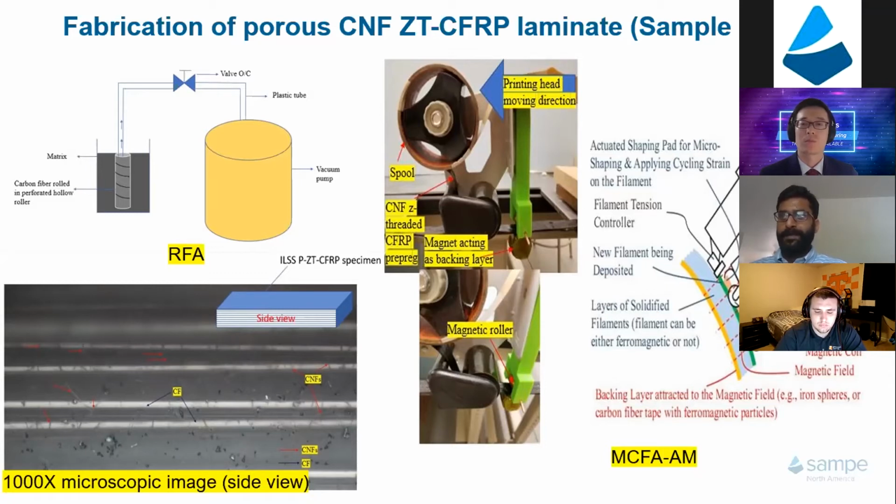But once the acetone is removed, the monomers get close to each other and they start to react. So there's a threshold where you can remove acetone without curing it, but after that, they start to cure. We are trying to find a sweet spot and are still struggling, because if you can't remove the acetone completely, then when you cure, the liquid acetone vaporizes, becomes bubbles, and pops the laminate open.